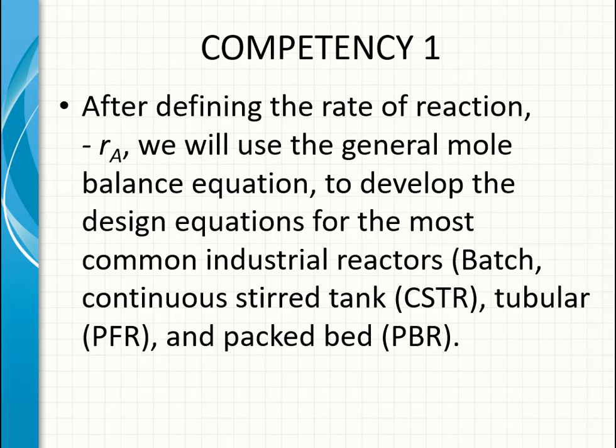After defining the rate of reaction, -rA, in this case minus rA because A is disappearing, a reactant that is going through a reaction to form a product, we will use the general mole balance equation to develop the design equations for the most common industrial reactors, which are batch, continuous stirred tank, CSTR, tubular, PFR, and packed bed, PBR.